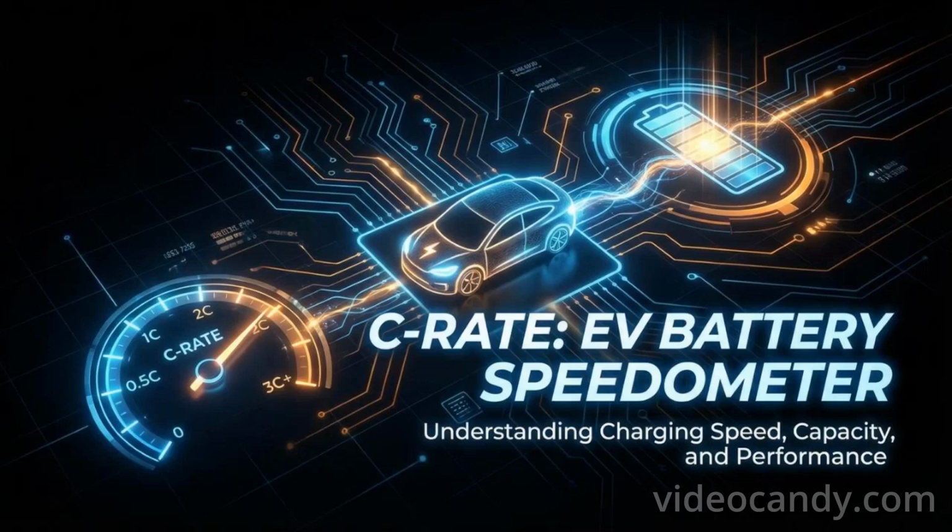The basic formula is that charging or discharging current equals the C rate times the battery capacity in ampere hours. For example, a 60 ampere hour battery at 1C charges or discharges at 60 amps, at 2C it's 120 amps, and at 0.5C it's 30 amps. This helps us understand how fast a battery can safely charge or deliver power.